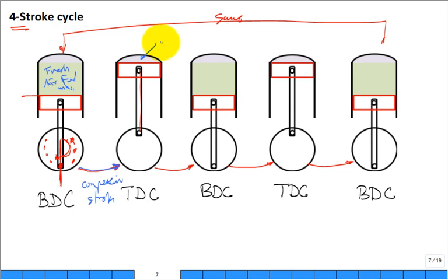Or if you're really going fast, it'll be 30, 35 degrees. And probably some people here can tell me what is the typical, at idle for their engine. They have a timing light. Maybe you've done that in the garage. Sat there, okay, I've got to disconnect this and that so that it's not going to be advanced. It's just going to be a natural advance. Maybe it's 10 degrees at 750 RPM.